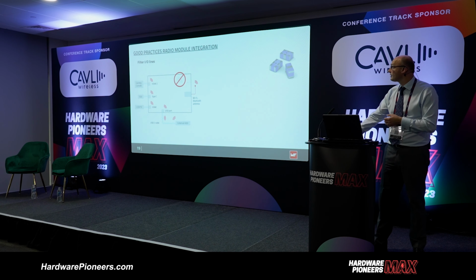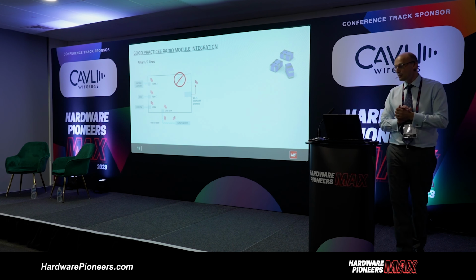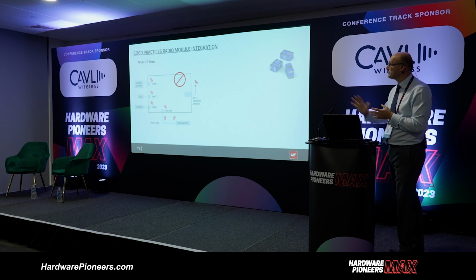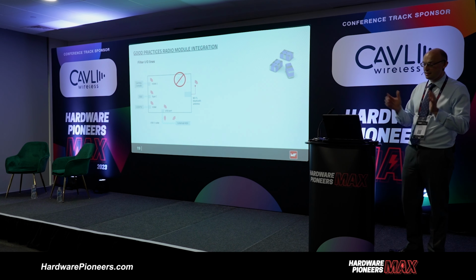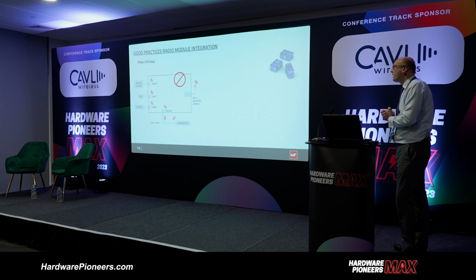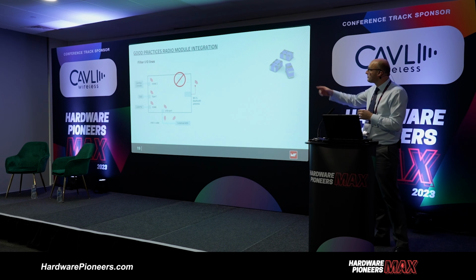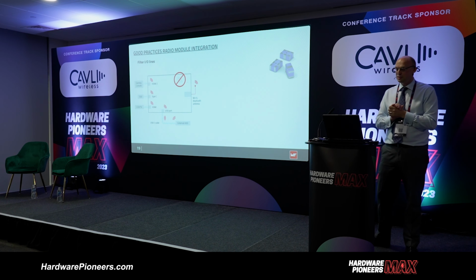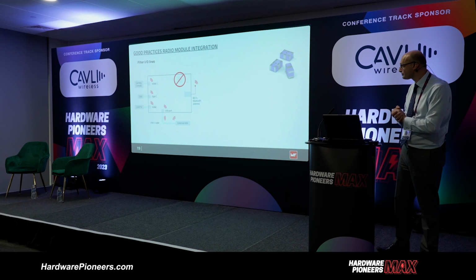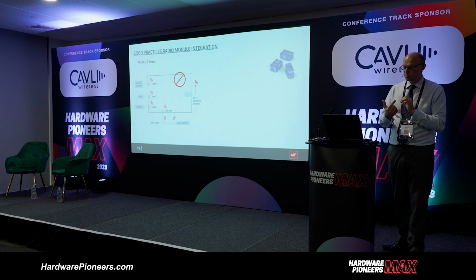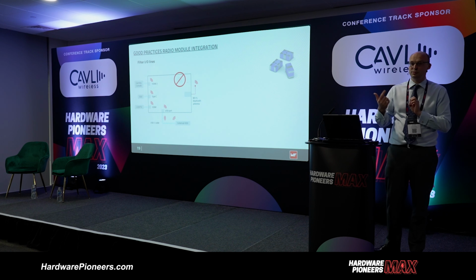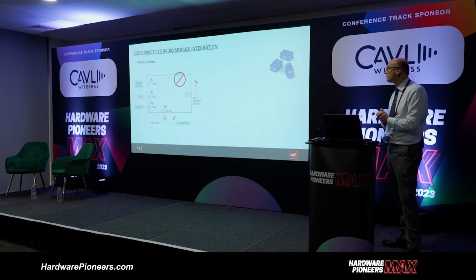Filtering of the I/O lines. Now the RF module itself is an intentional transmitter. It could be transmitting, let's say, 868 megahertz, 2.4 gigs, radiating off the antenna. That intentional signal could then recouple back into your actual product. By coupling back into your product, typically through capacitive coupling, it may now feed back into the module, and you now get an instability in the actual RF circuit.